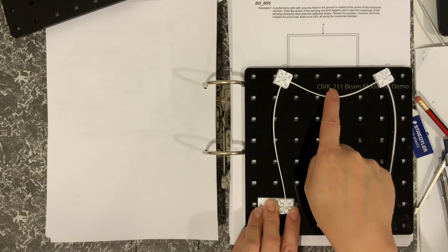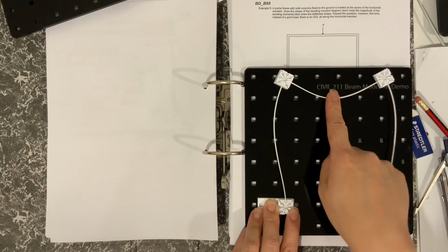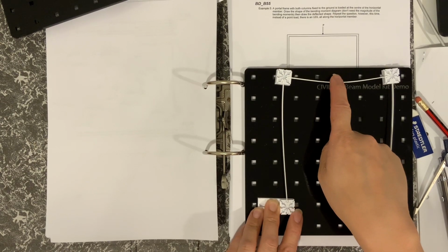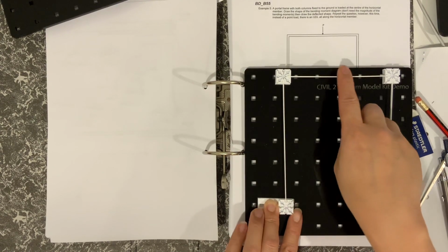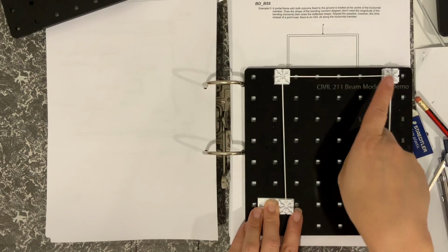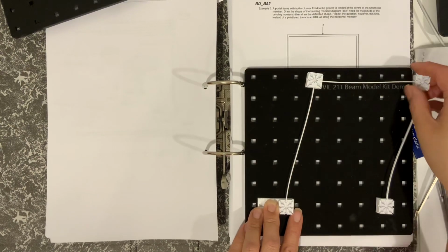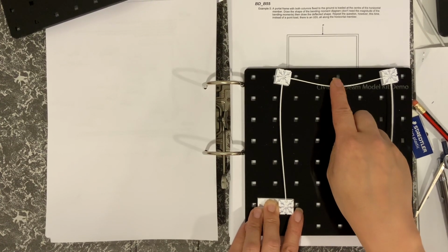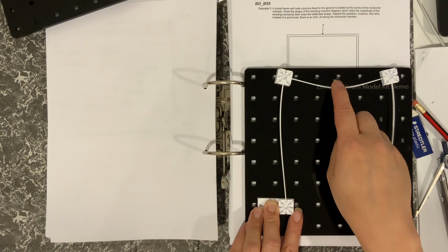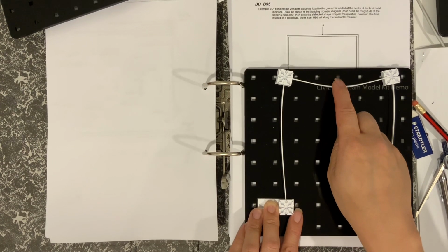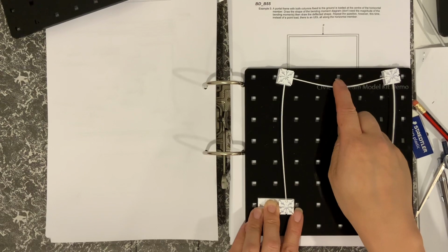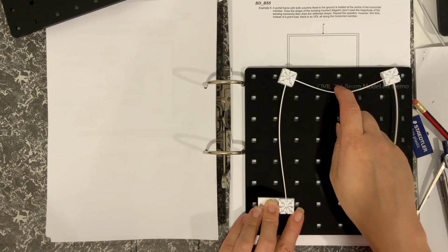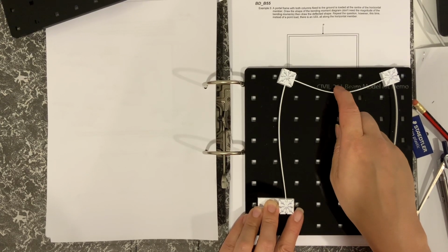So from there you can see what the deformed shape of the frame is, and remember when you look at this, these joints do move, of course, but if the load is exactly right in the center, then the frame is symmetrical, and so the frame wouldn't want to sway due to symmetry. Okay.